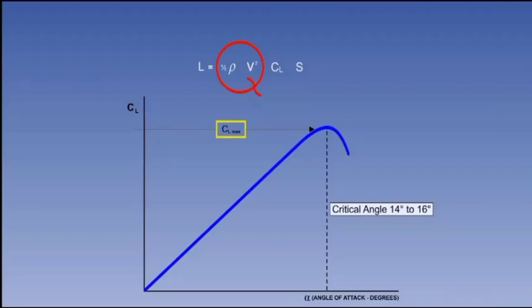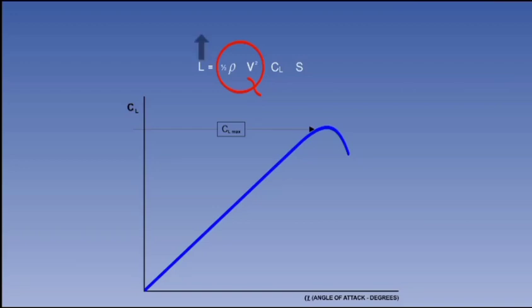The angle of attack for CL maximum is constant for a given configuration. If more lift is required because of greater weight, a greater dynamic pressure, that is more speed, is required at a given angle of attack. The greater the weight, the higher will be the minimum dynamic pressure or speed required for level flight.